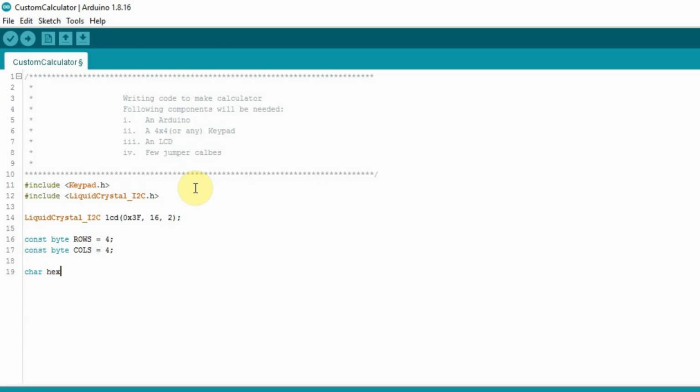Now let's start constructing the key matrix. In this key matrix, I'm going to construct the rows and columns in the same way keys on the keypad will behave. I'm going to use 4 mathematical operations in this calculator: plus, minus, multiplication, and division. And also creating one key to reset my calculator and naming this key C. And the last key would be E, that is representing the enter, and pressing this key will show the end result of the calculator on the display.